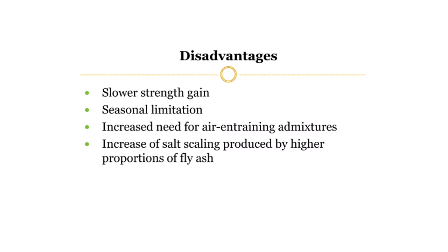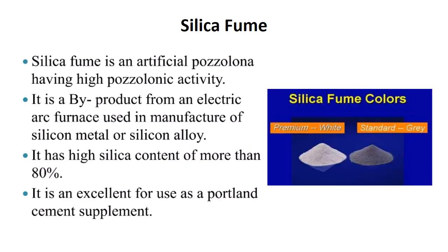Some disadvantages: it has a slower strength gain, seasonal limitation, increased need for air entraining admixtures, increase of salt scaling produced by a higher proportion of fly ash. Next